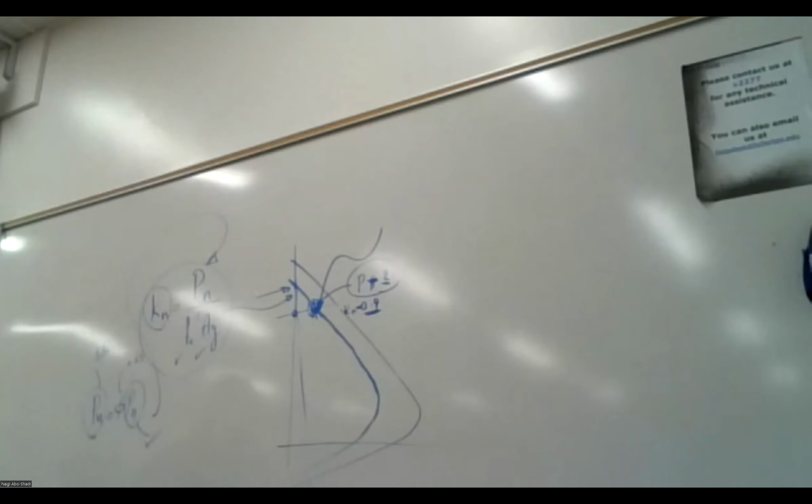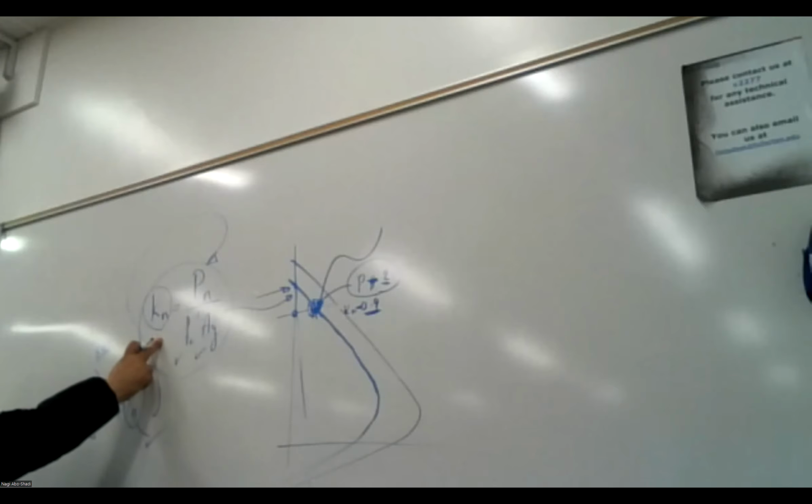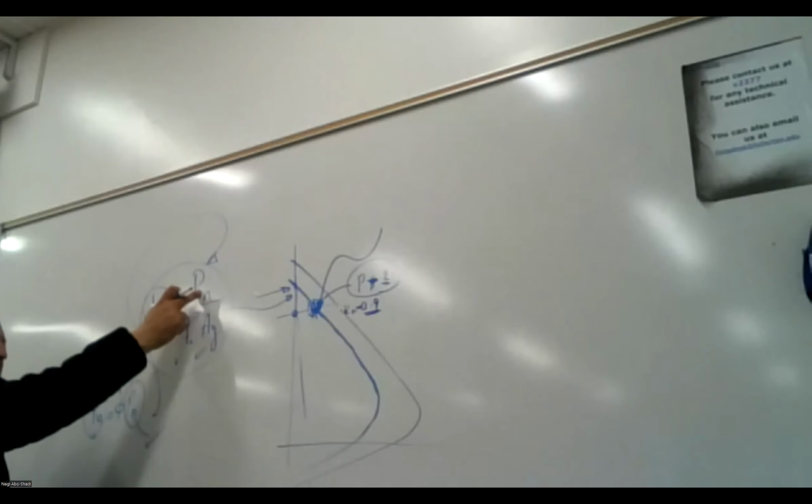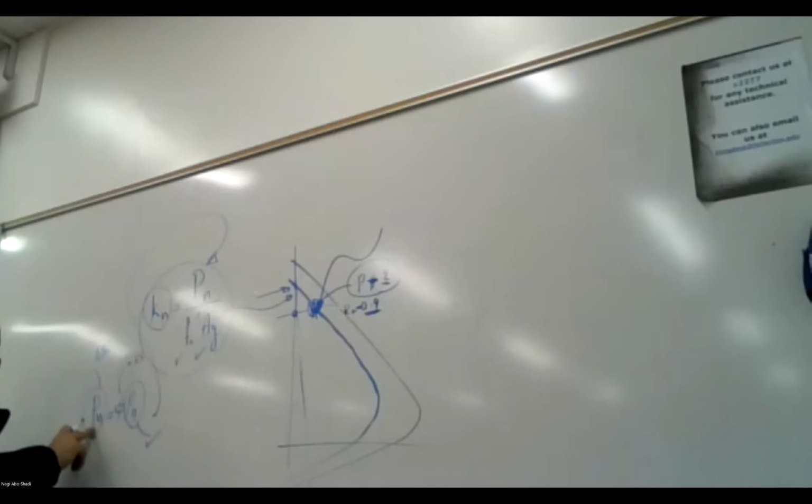So once you find it, we don't have to plug in for Kn. You just figure out Kn from this equation, right? How did you do it? It says give me Pn. Where did you get Pn from? You take P sub u, your demand, and you divide by the phi factor. You remember this equation? So we start here.